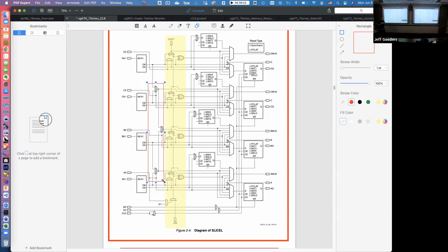I know that you said you'll get to this later, but you said that there's a configurable shift register. Can you get at that by just making a shift in your Verilog code? We're just about to start to talk about that. Okay, how do you design to take advantage of this stuff? In 220, you prove to yourself that you can write arbitrary SystemVerilog code and magically it gets mapped. What if you really know you want to use a shift register, but you don't want to use 64 flip-flops? You want to take advantage of the shift register that's built into the slice M.